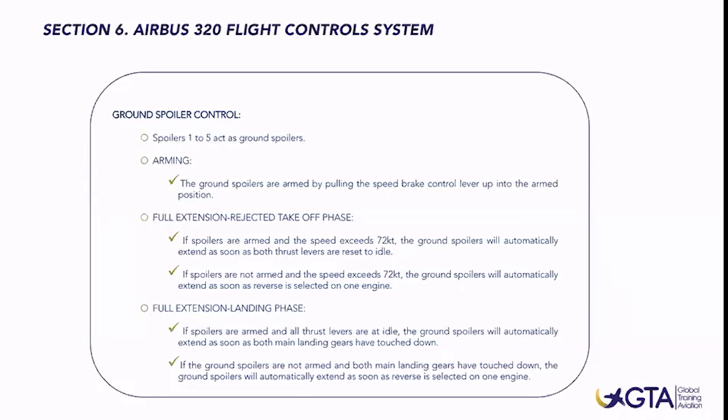Same for landing. Can we land with the spoilers disarmed? Yes, we can, but that's a non-standard procedure. For landing, the standard procedure is to arm the spoilers, I mean, pull this lever up.